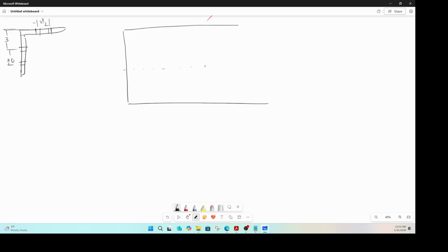So that is the center line, and then these holes are also zigzag. That's the top section there. There's the center line, and then these holes here are obviously at that location like that. Okay, and we'll do a detailed video about this. But when the holes are staggered like this, there are a couple of rules that you need to follow to calculate your net and gross area, and that is what we'll look at in our next session.